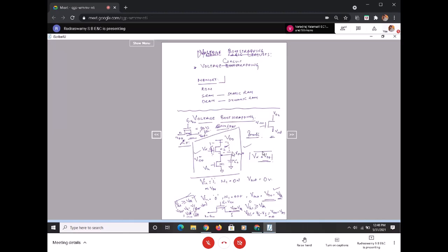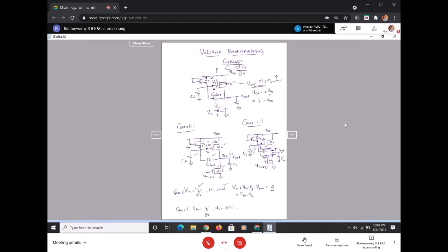So how to make this something like VDD, and make sure that your Vx voltage is increased beyond VDD? It is not that by applying one more VDD from somewhere, no, but just to make sure that Vx is raised above some point. In order to do that, we have this kind of structure, wherein when Vin is 1, Vx is driven to VDD minus VT3, because of M3, that is the gate.